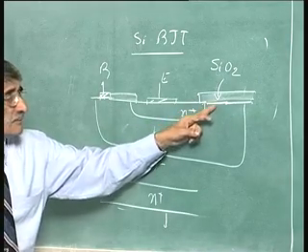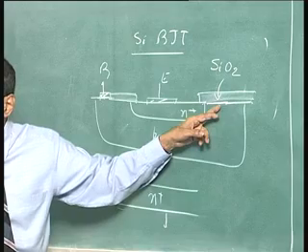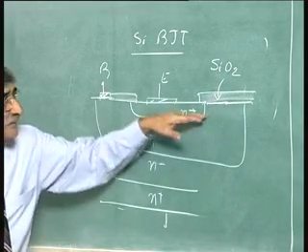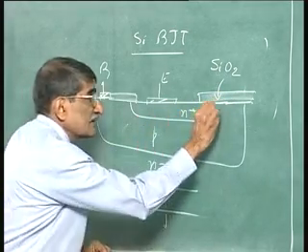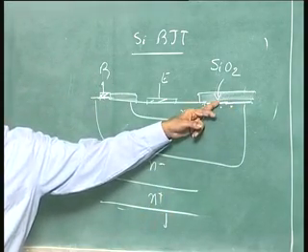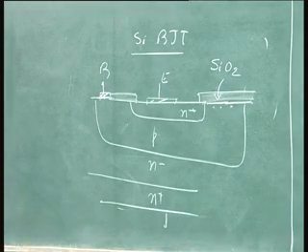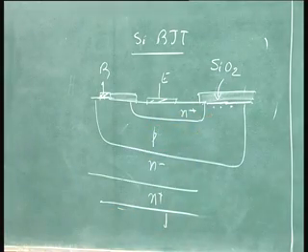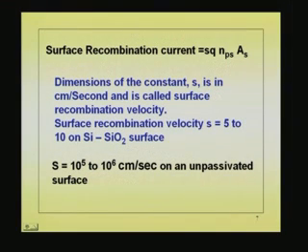The electrons are lost to the surface due to transport of the electrons from here to here. In fact, whatever bulk concentration is here nearby diffuses into the surface to recombine there. So, what we are talking of is the surface recombination component. Just like the bulk recombination is proportional to the carrier concentration, the recombination at the surface also is proportional to the carrier concentration, Np near the surface, just adjacent to the surface. So, it is per centimeter cubed, okay.